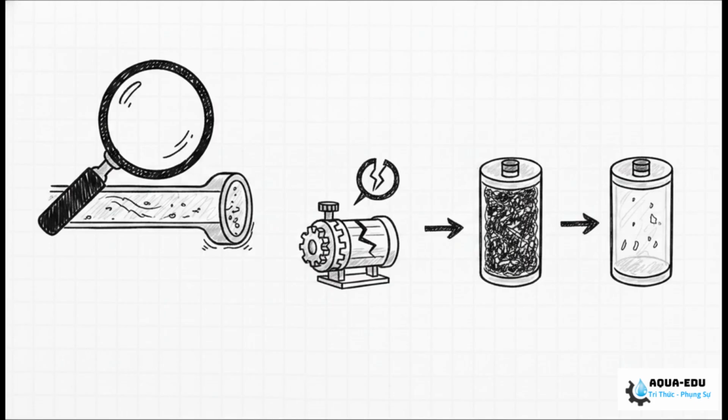It has to strictly stay below 1 NTU. Then look at your silt density index. It absolutely must be under 2 for borewell water and under 4 for surface water. Finally, go physically inspect those 5-micron cartridge filters. If they're bypassing or failing, your insanely expensive RO membranes just became your new multimedia filters. And that is an absolute nightmare.